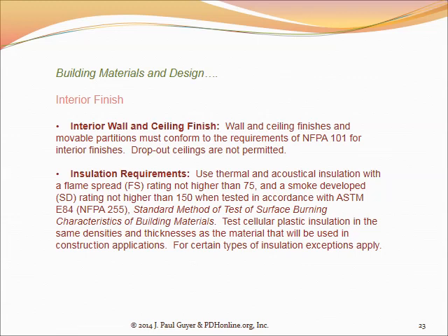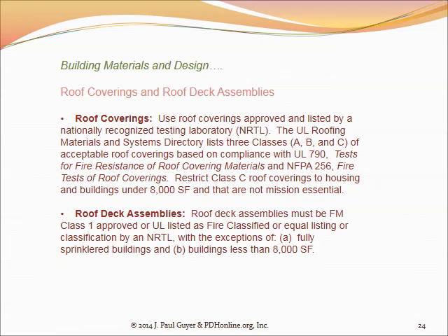And so that, again, is all by and large mandated by codes. And the roof coverings, again, the roof is a very vulnerable element in a building in the event of a fire, and the codes mandate certain levels of fire-resistive construction for the roof structure. How are these fire-resistive characteristics determined? Again, it's Underwriters Laboratories testing them, or Factory Mutual.